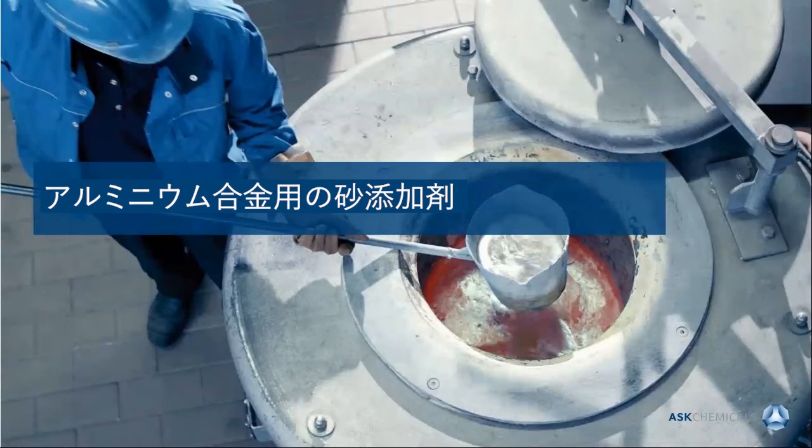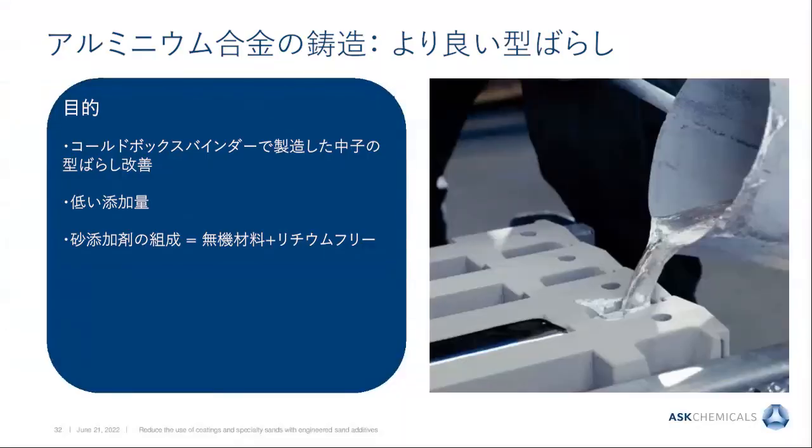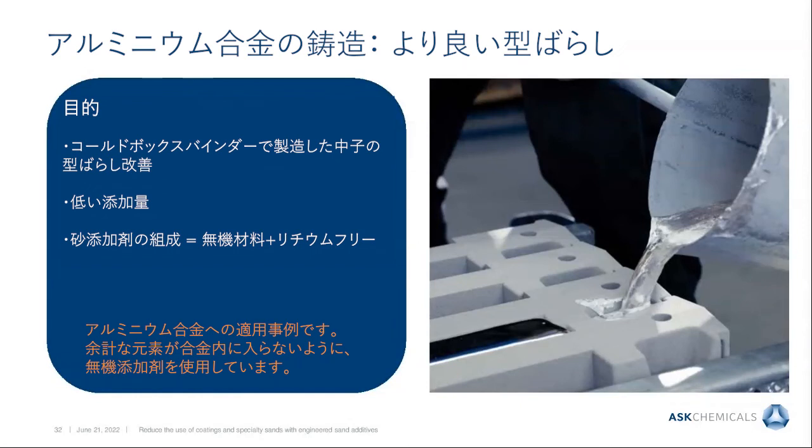What about additives for aluminum? You as an aluminum foundryman certainly would like to demand that the shakeout with cold box cores must be improved, because this is a big issue often. And you would like to have a low addition rate of the additive. For the additive formulation, definitely we need to have an inorganic additive because of the gas sensitivity of aluminum, and we want to have a lithium-free additive because of the cost boost, which I mentioned before.